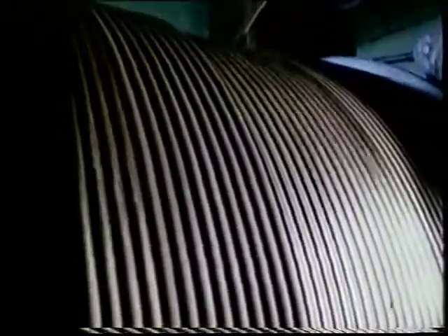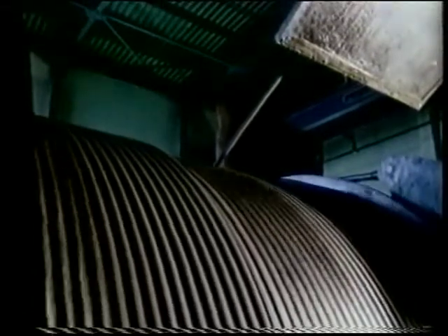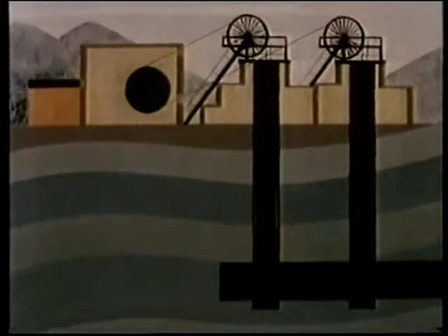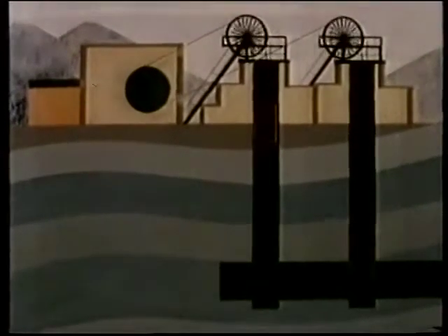This information determines the diameter of the rope required, and in turn the rope size will determine the minimum drum diameter to allow for rope bending. The drum itself carries not one but two ropes, counter-wrapped, so that while one is wrapping, the other is unwrapping. This means when one cage goes up, the other goes down. Running two cages from a single drum reduces the torque that has to be supplied to the drum.